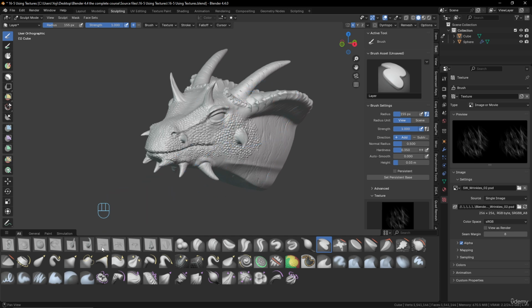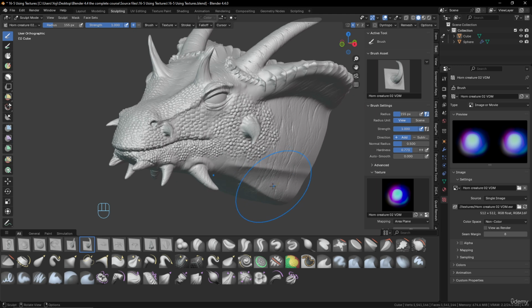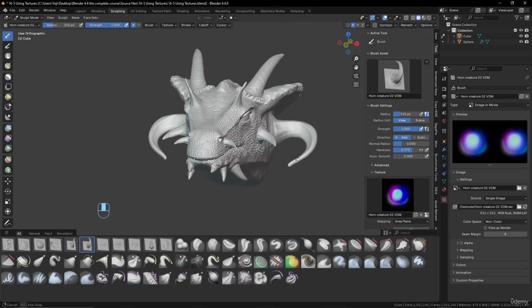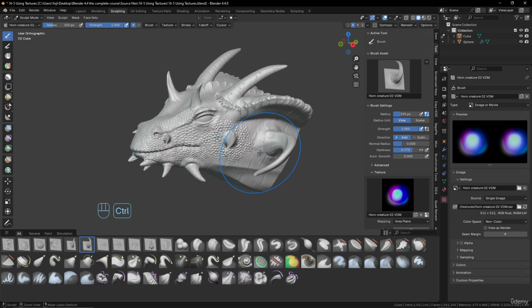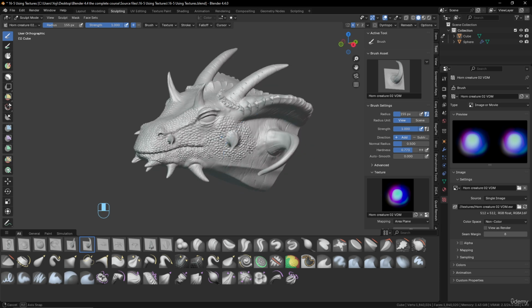It's so interesting to play with this and add more details to your design very easily. Like for example, here you want a big one, you add a big one, and that's it. You remesh everything if needed with Ctrl R, and after you have what you want.